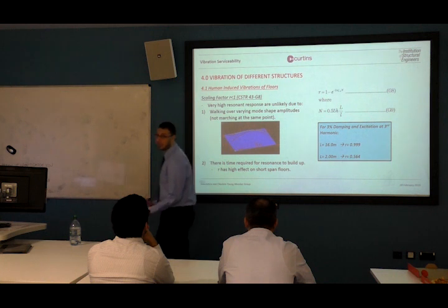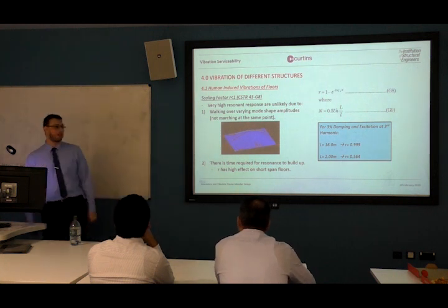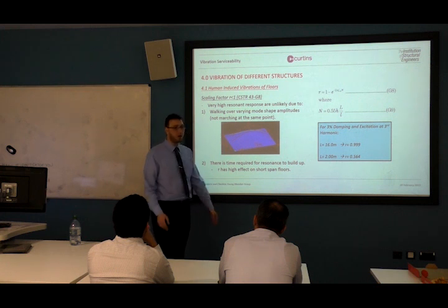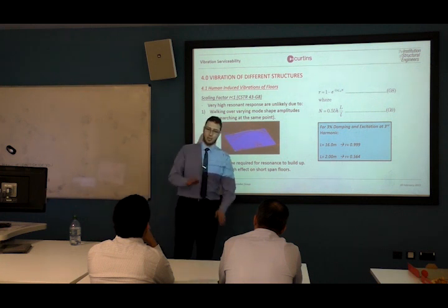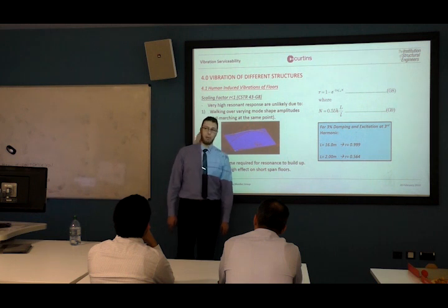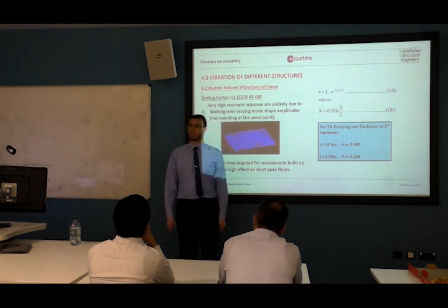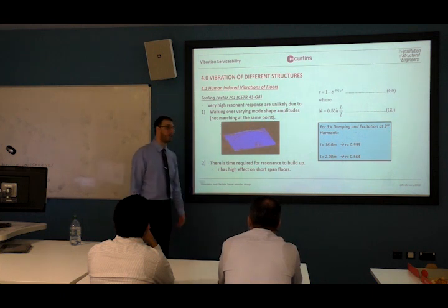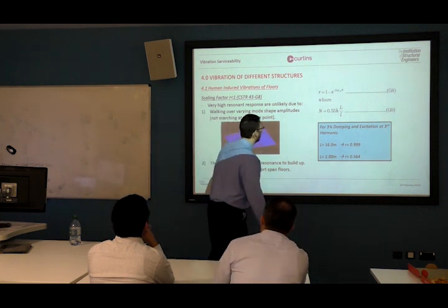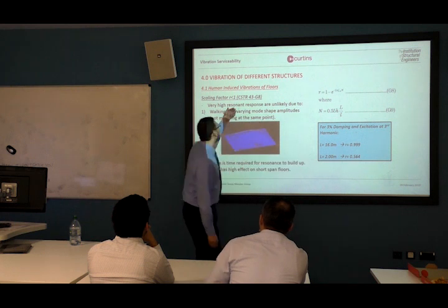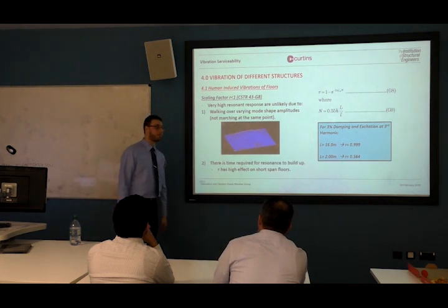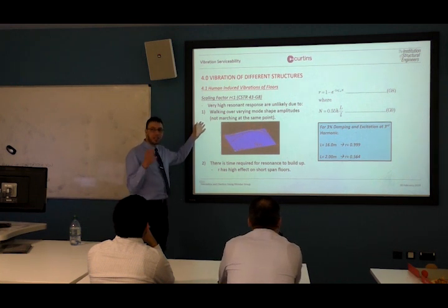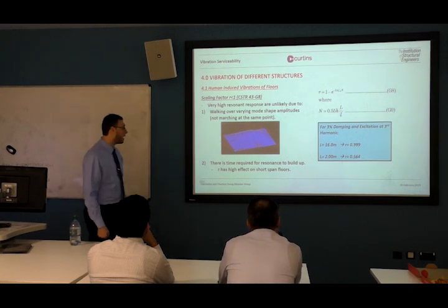It's a very realistic type of analysis. Now, British codes and documents say no, the way we do it, we select the worst case and apply the load like someone's marching. But this is not the case, we're not marching, we're walking. That's why we have to reduce the response we're getting. Because we're not marching at the same point, there's a reduction factor that needs to be applied.